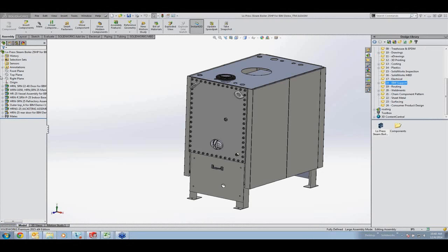But it's still not quite in the right position here, so let me flip that angle there. And it will show the preview. But I have the wrong bend position type here. It actually cannot create this bend with this bend position. So I need to change it to the bend outside. It has to do with the sketch being on the edge. So there we go, there's a nice preview there. I'm going to go ahead and accept that. And that is all the updates for sheet metal in 2015.